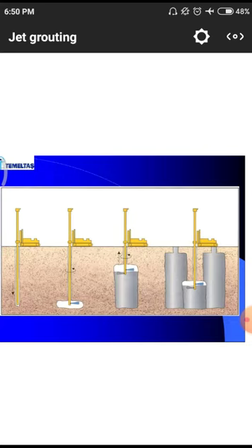Normally, whenever there is a high load, due to those loads some of the dams will face cracks. Due to those cracks, they lose some quantity of water. To restrict this loss of water, they have to fill these cracks with the help of this grouting method, whether it is above the ground level or below the ground level.